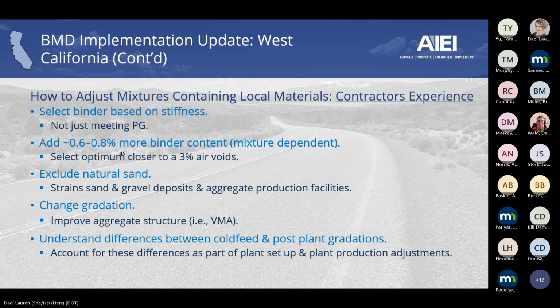The key aspect was, because they were failing the cracking test that was done at intermediate temperatures, what they found out is that the intermediate temperature criteria matters. How far are they from that criteria? So two binders, one that is passing that intermediate temperature criteria significantly versus the other one that was barely passing. It made a big difference on the mixture testing.